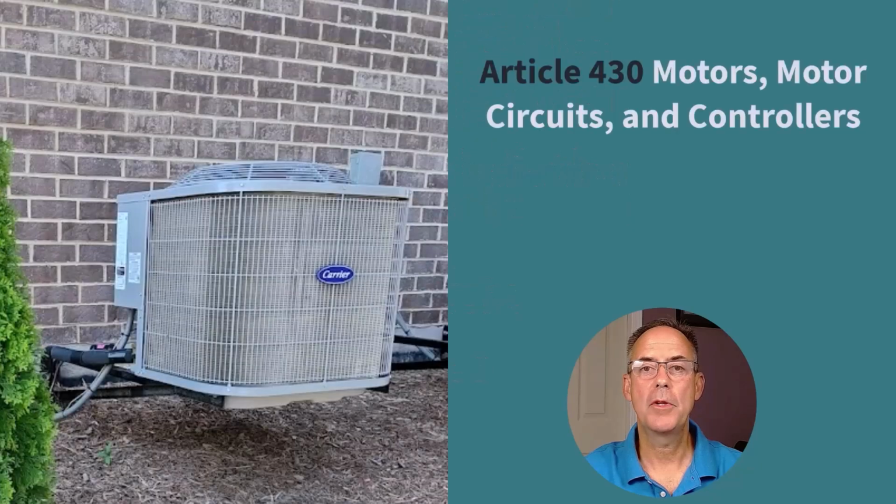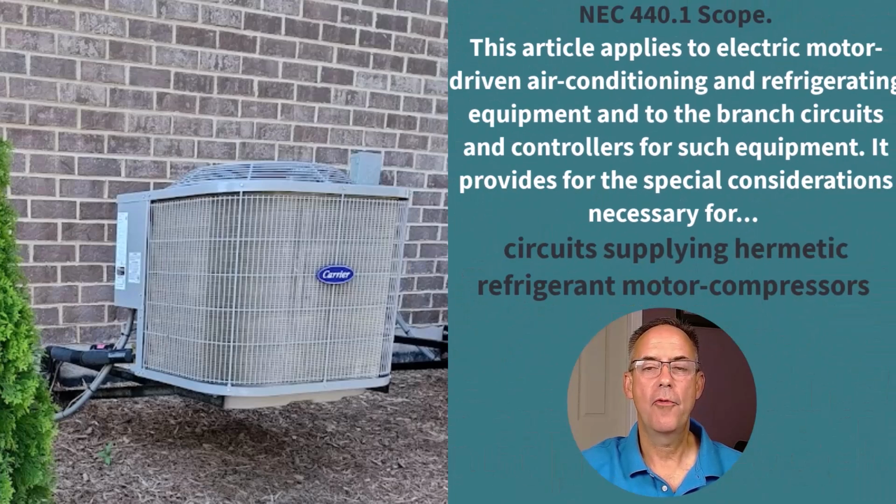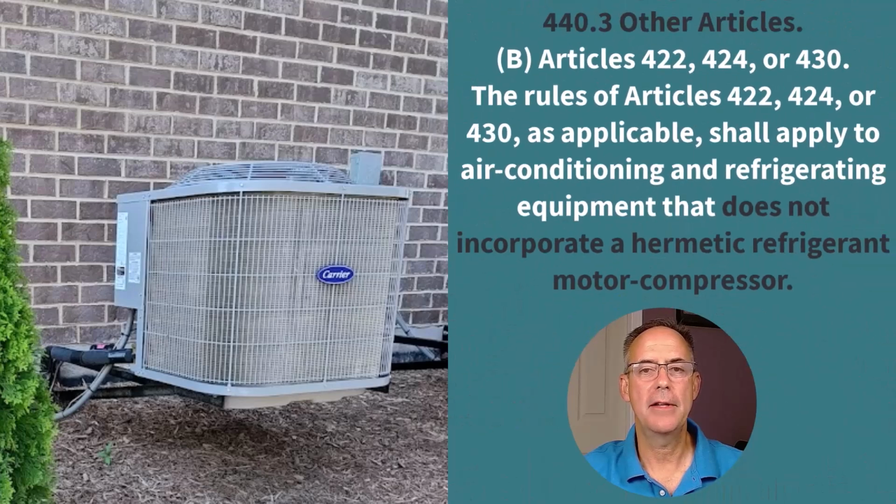Typically for sizing motors, we go to Article 430 in the NEC, but for refrigeration equipment and air conditioning, the NEC sends us to Article 440. Once we're in 440, if we go over to 440.1, the scope article, it tells us that we're in the right spot. This is for refrigeration equipment or air conditioning units, but it also says that it's specifically for hermetically sealed motors and compressors. If we read a little further down, we come to 440.3, which is called Other Articles, and it tells us that if it isn't a hermetically sealed motor, we're going to refer back to the typical sections of the NEC that we would follow for other type motors.